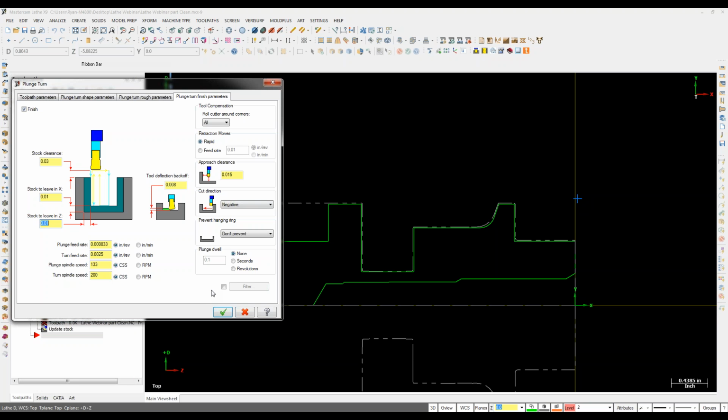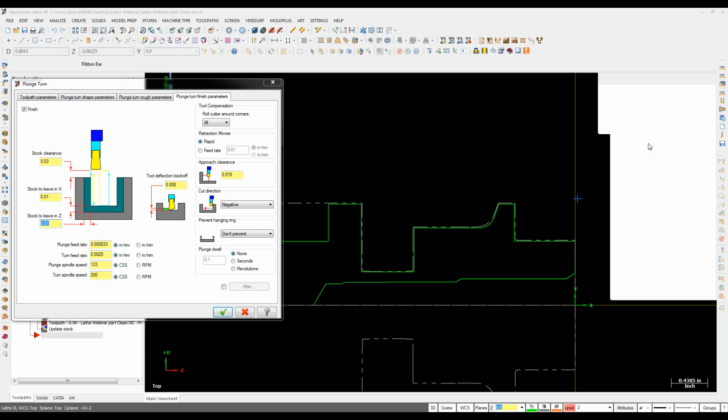So the tool path is doing... eventually, had a customer in our area here that was using one of these new plunge style tools, originally developed with Carr about 4 or 5 years ago, but basically all the lathe manufacturers have come out with similar tools. The way they work is they're designed to deflect a little bit. This customer was freaking out; they were getting, I think, 4 thou off on every part. It turned out the difference they had to make was to use a plunge tool that was a regular groove. So if you are getting into any of these new style plunging tools, I definitely recommend checking out this particular tool path.